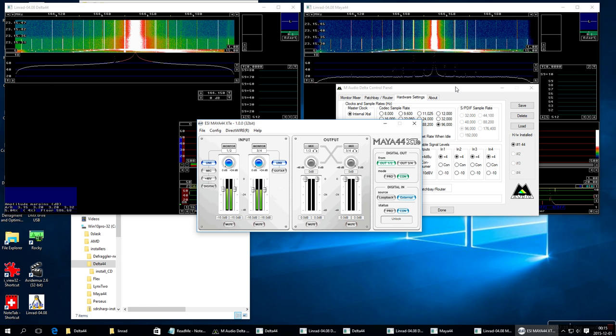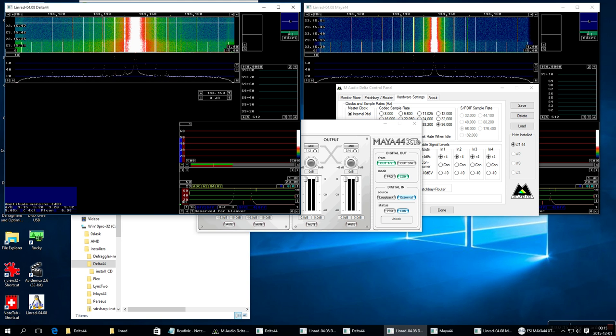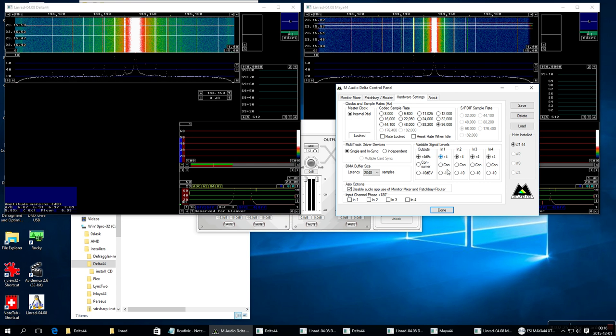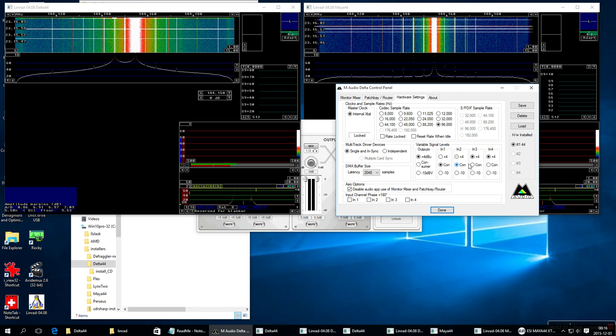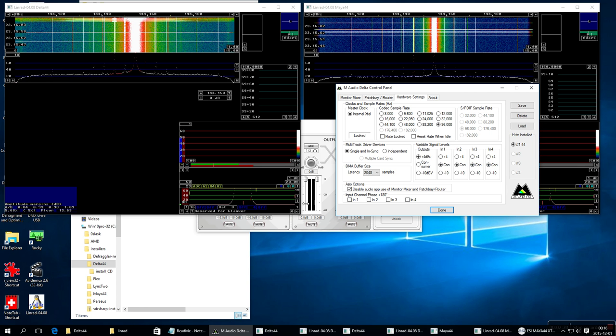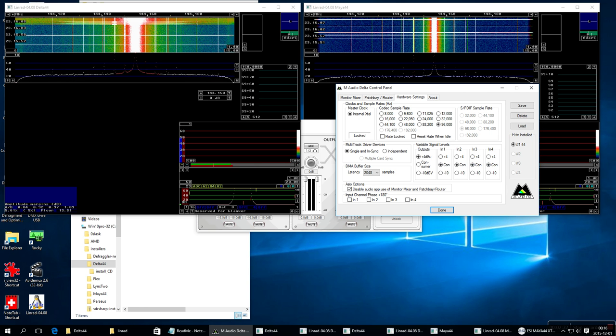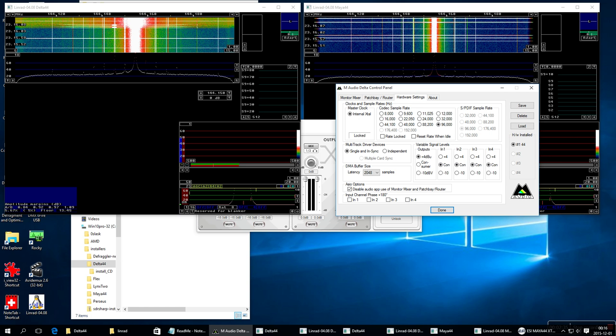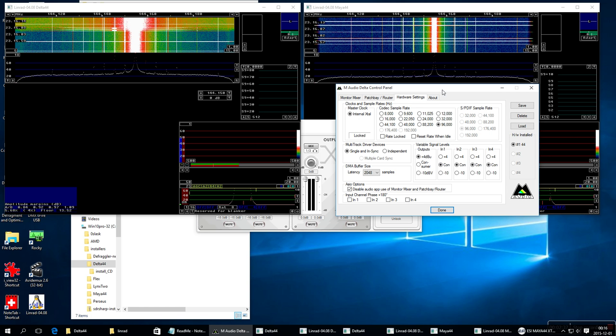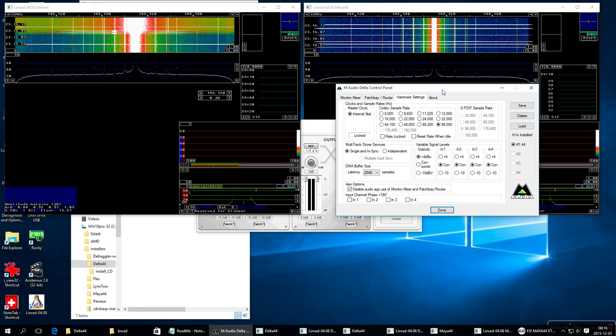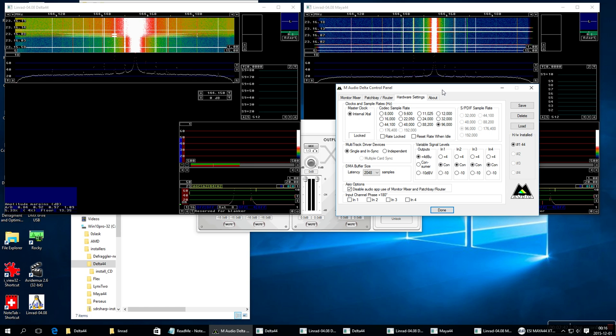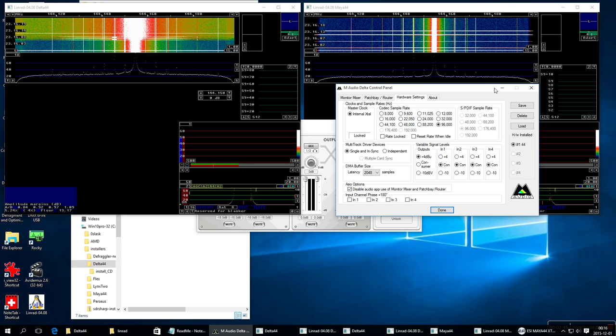In the Delta44 I have to press Z to clear the detector. So we have 6.9 decibels of headroom, means I can go to consumer mode without saturating. And now saturation happens very close to the same level in both the IQ Plus and in the Delta44.